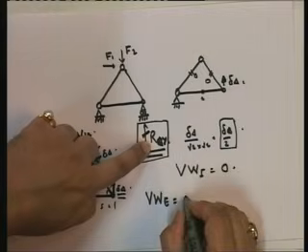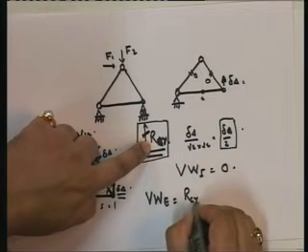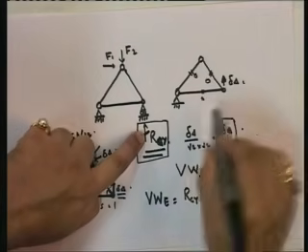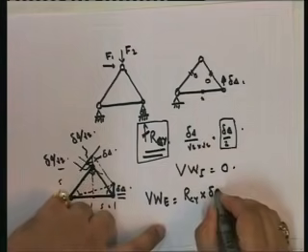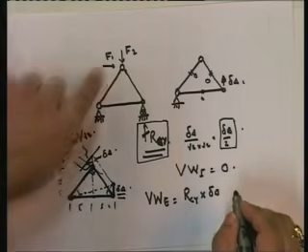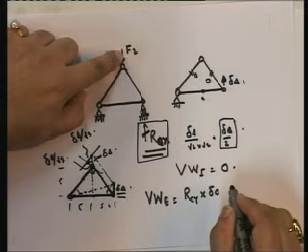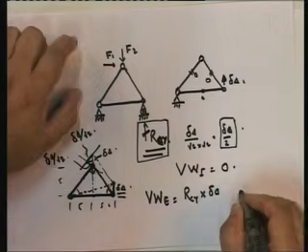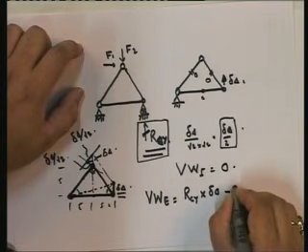First is this, RCY multiplied by d delta. Note that this is up, so the work done is positive. Now next, this force, F2, how much is it undergoing? D delta. But F2 is downwards, displacement is upwards, so it's negative work.